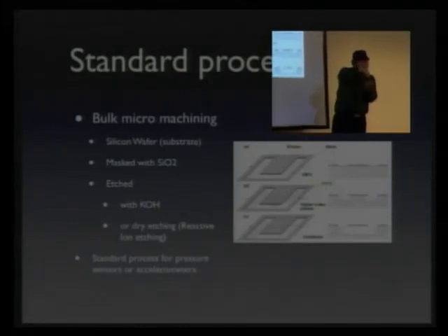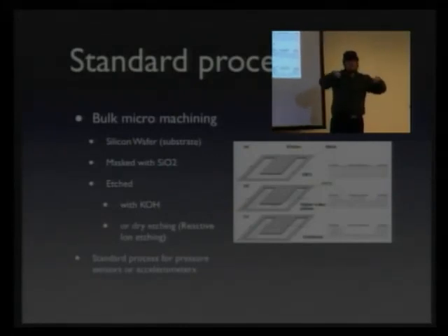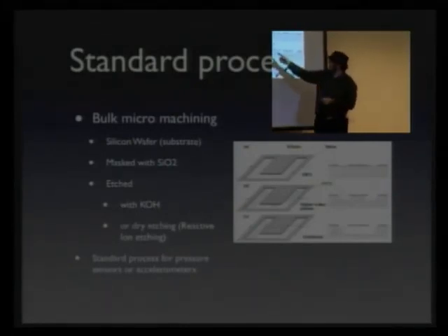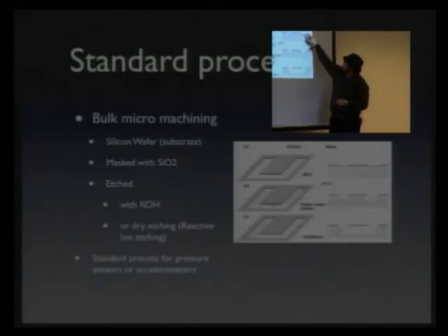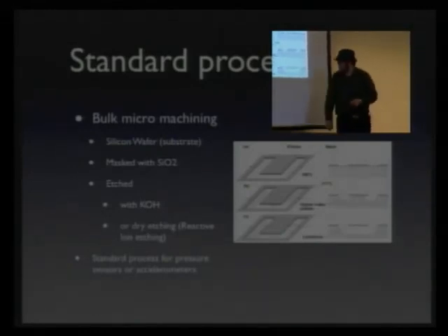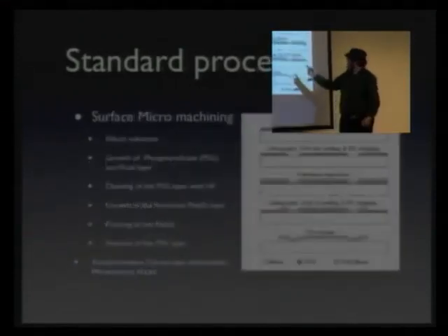If you have a piece of metal and you start to etch it, you will get a mushroom-shaped cutout, but you won't have this when you use silicon. I'll show later why. So you make an opening like this, and then you basically under-etch the cantilever here, and then you have a free cantilever. And this is an accelerometer.